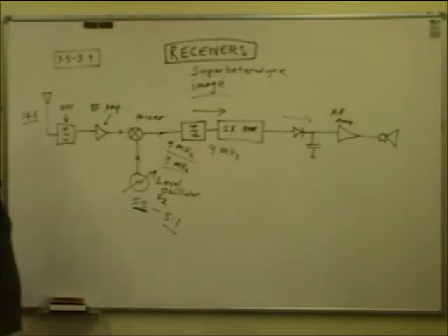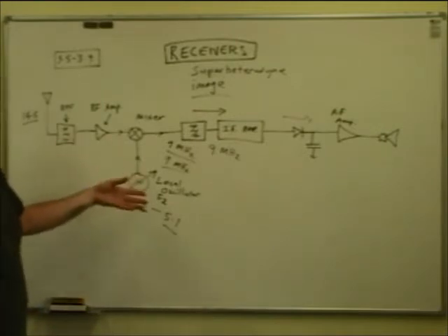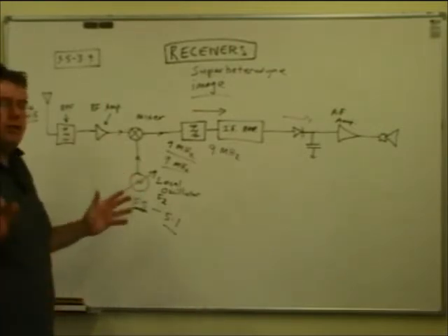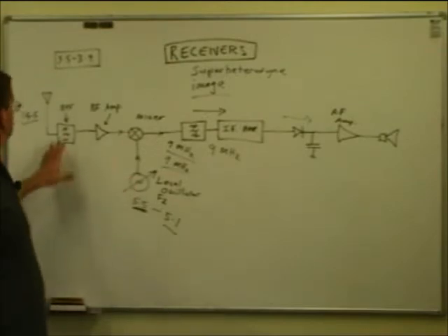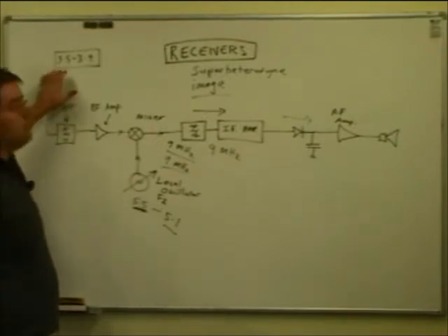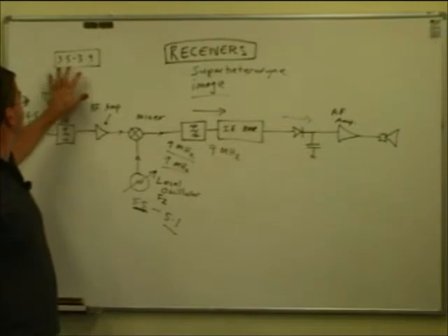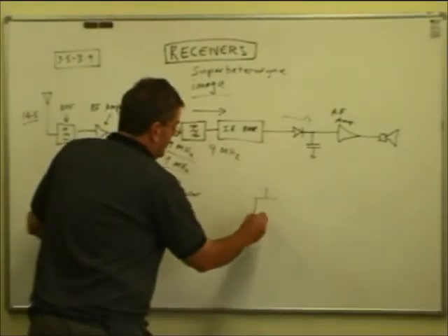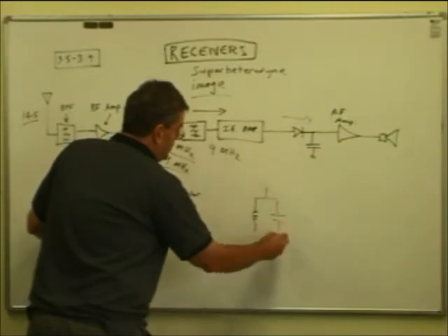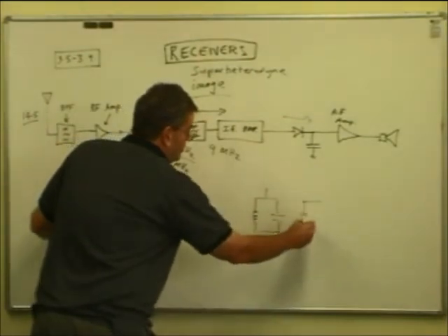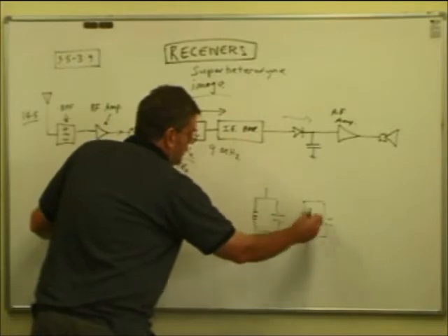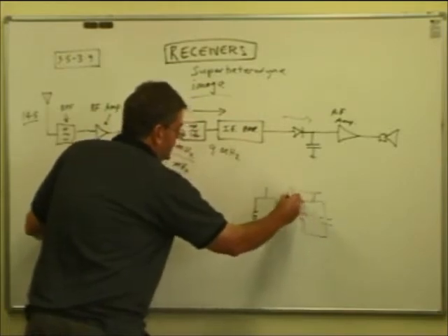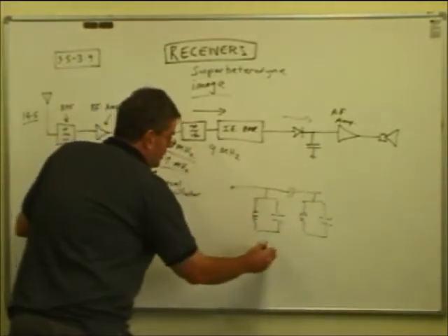So you might say, well, hang on, aren't those bandpass filters expensive things? Well, no, they're not, if we want to make it quite broad. It's not too difficult to make a filter pass that 400 kilohertz range with a couple of tuned circuits. You don't have to know this much detail for the exam, but we mentioned this in filters and resonance.